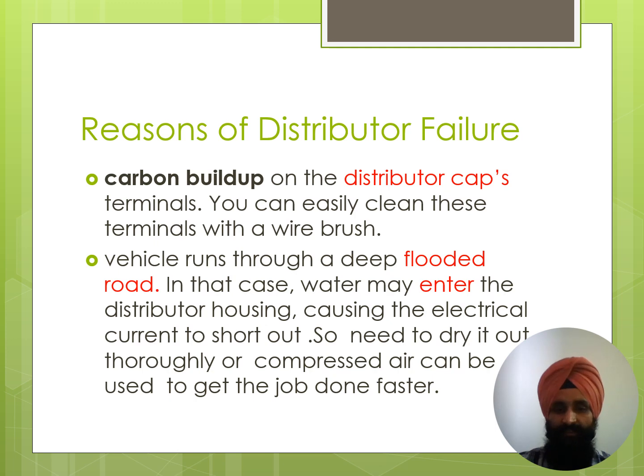The simple reason is that whenever a vehicle crosses a flooded road, water may enter the distributor's housing. It will cause the electrical current to short out. So in such situations, avoid flooded roads, or if something like this happens, try to dry out the distributor cap with compressed air. That would be the best thing.